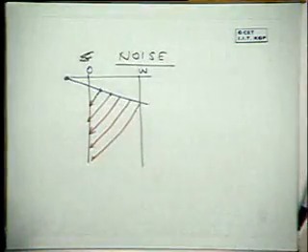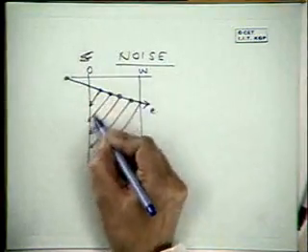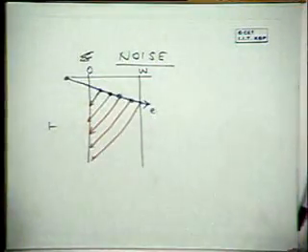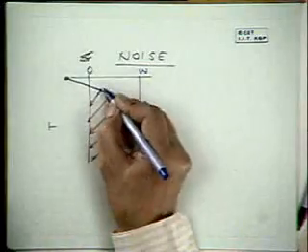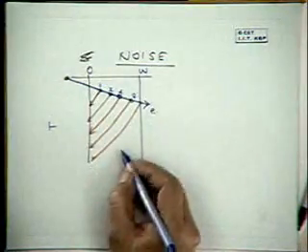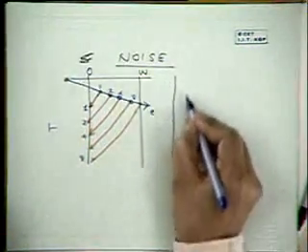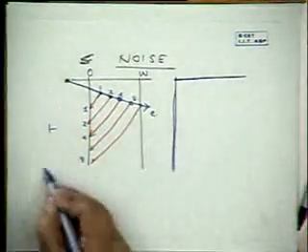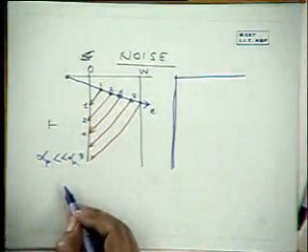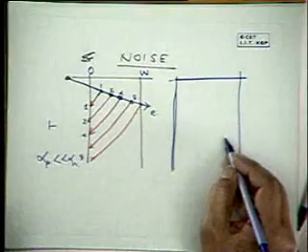Whereas the electron is proceeding, the electrons are multiplying, okay. The holes are multiplying, but they are not avalanching. Okay. So the number of electrons is going up, say from 1 to 2 to 4 to 8, etc., etc. And the holes are going up 1 to 2 to 4. Okay. Now suppose you have the other case; this is the case where alpha P is much less than alpha N. Suppose we have the case where alpha P and alpha N are both appreciable, then what happens?